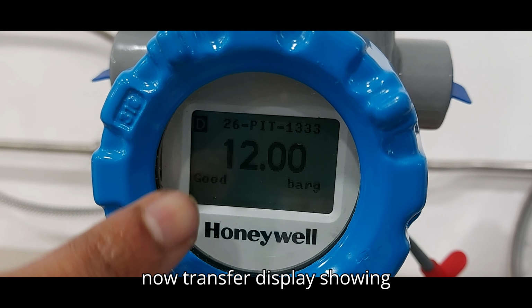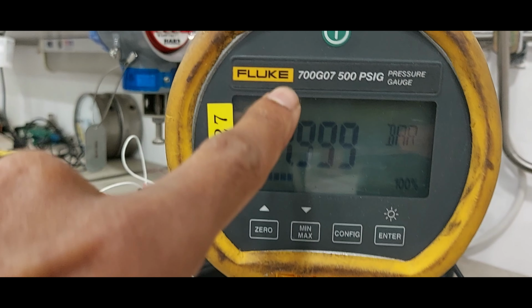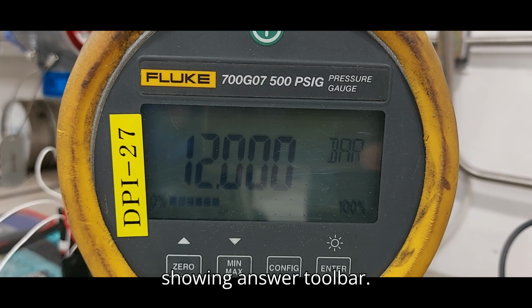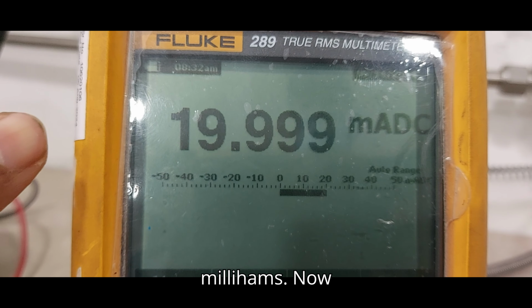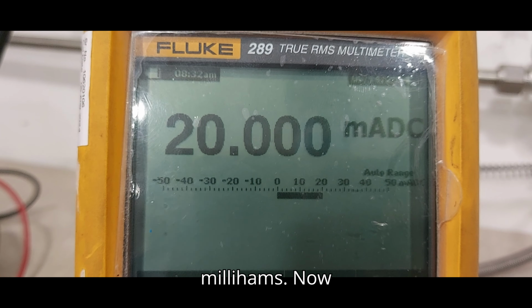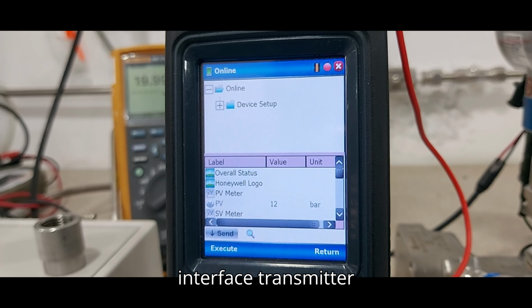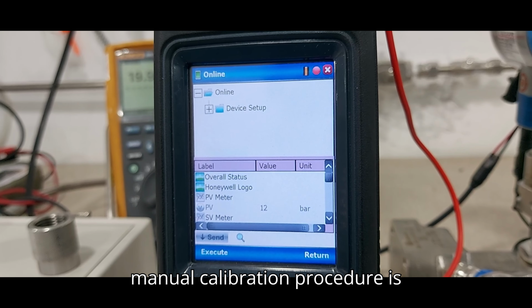Now the transmitter display is showing 12 bar. The reference meter is also showing 12 bar, 19.999 milliamps. Now the ST800 HART interface transmitter manual calibration procedure is completed.